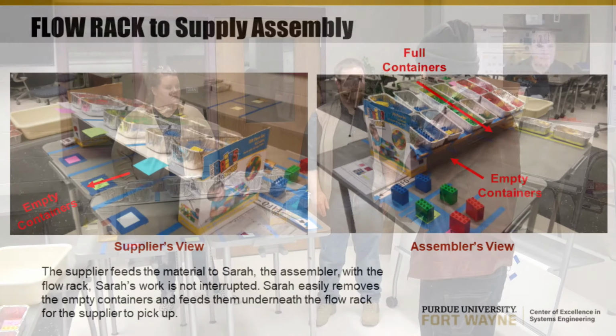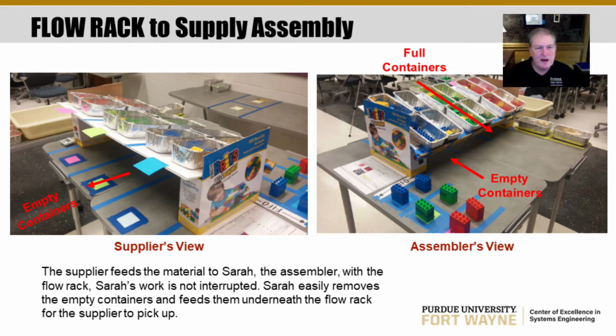Yeah. In round 3, we calculated takt time to be 8 seconds per unit. The consequence of understanding takt time is that we saw Sarah as a delay to meeting takt time in assembly. So part of the issue was managing the container flow into and out of assembly.